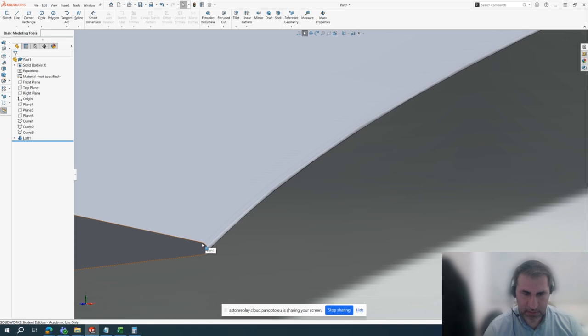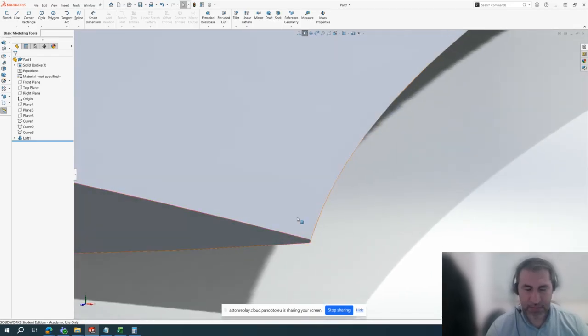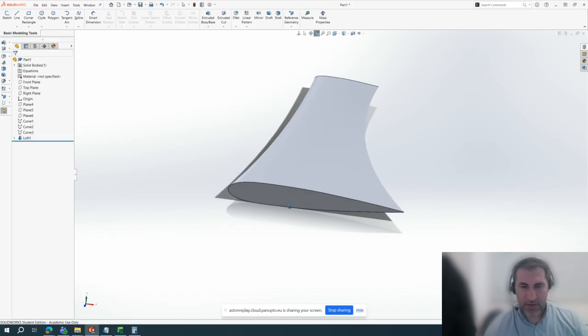If you had a line here, there would be a separate surface here, and for CFD modeling, for example, you would need to create mesh for that because it's very tiny. The mesh should be tiny and you have lots of non-orthogonal cells because of only that. And in that way, I just created one surface on top and one all connected to here. Great. So now let's create the other part,